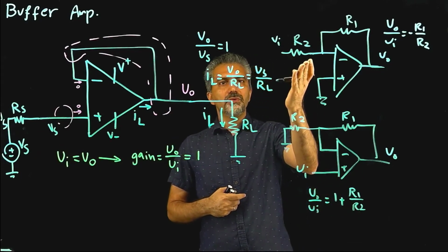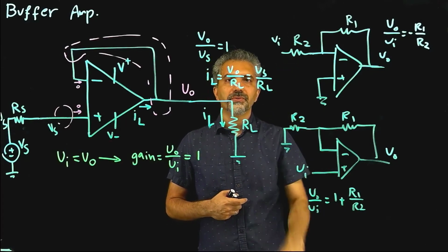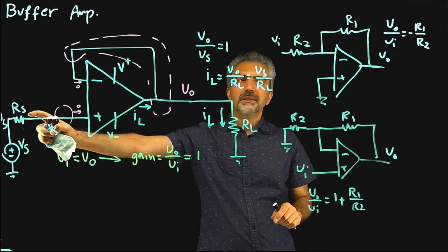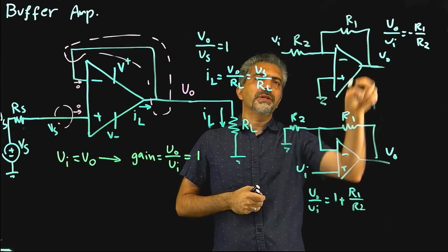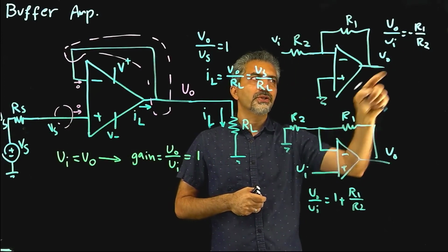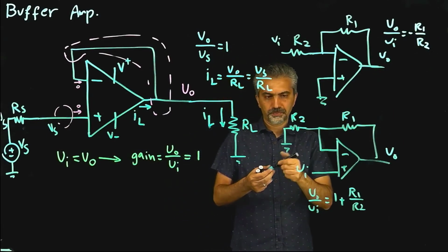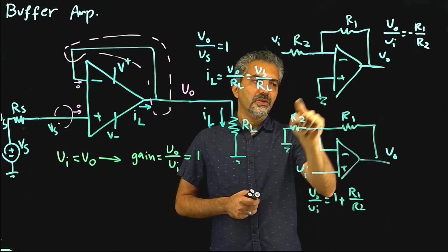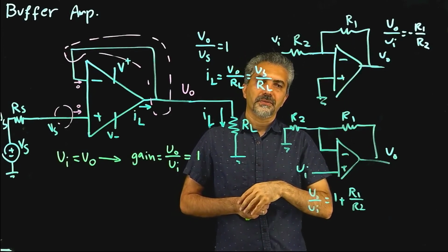Whereas if you use this kind of amplifier, the internal resistance of this amplifier is actually R1. You can quickly calculate that. And therefore, if the internal resistance of your source is large, the total gain of your amplifier is not going to stay the same as that equation. You're going to get a voltage divider, and this would go down. Your gain is going to go down. Therefore, in such situations, using this configuration is preferred over that configuration.